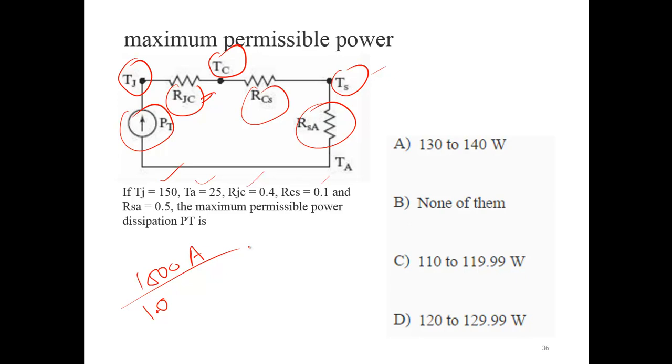It's very easy. It's not only 1000 amps; sometimes you have a 4000 amp device. Even with 0.5 volts, you cannot have 0 volts, these devices are finite, you can have 2 kilowatts. That's the biggest challenge, to get rid of the heat, and heat is what is going to destroy a device. Please calculate that number.